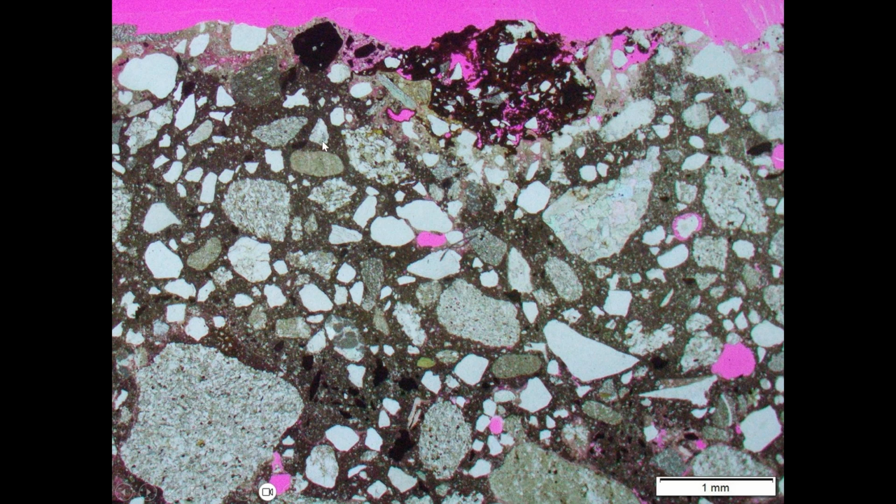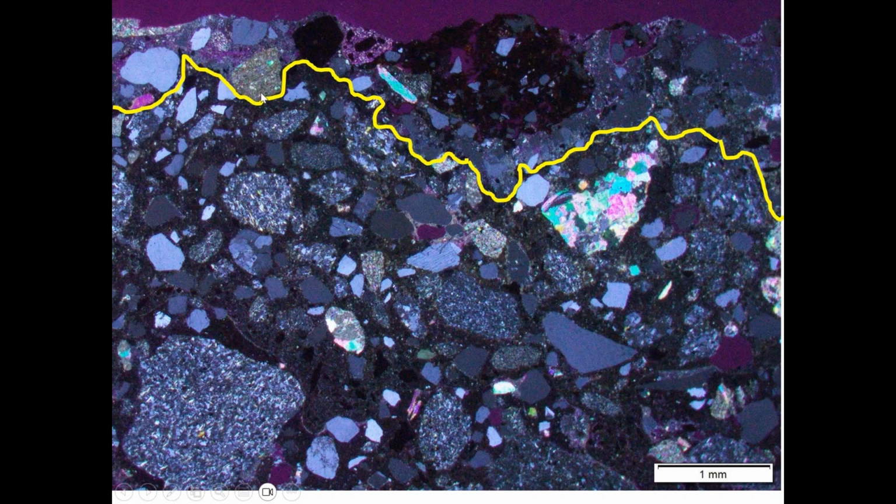When I look at this under polarized light, I can see that the surface down to that yellow line of this concrete has been carbonated. So why did that embedded steel mesh oxidize, which was causing the tiles to pop off, right? And that was the problem. The formation of iron oxide did that because, well, two things were happening, I think. Clearly the paste around it was carbonated, so the passivity layer was removed, and therefore oxidation and corrosion could just go to town. And also you're in a swimming pool with chlorine in it, right? So the chloride is probably getting in there too.